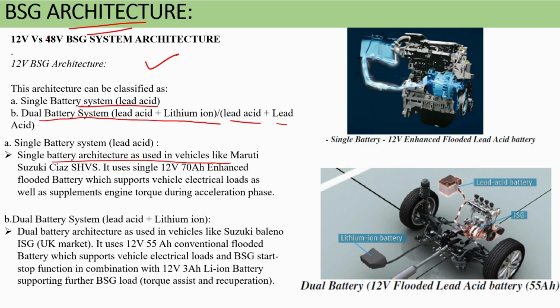So the single battery architecture is used in vehicles like Maruti Suzuki. It uses a single 12 volt 70 Ah enhanced flooded battery which supports the vehicle electric load and supplements the engine torque during the acceleration phase. So which we have already discussed.